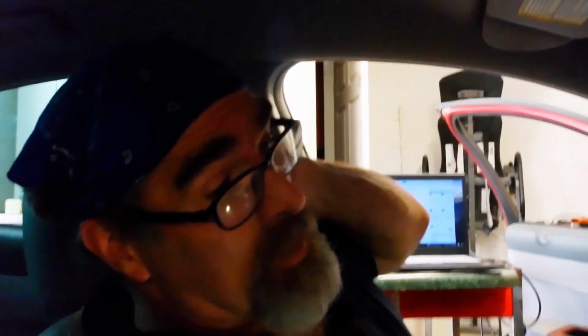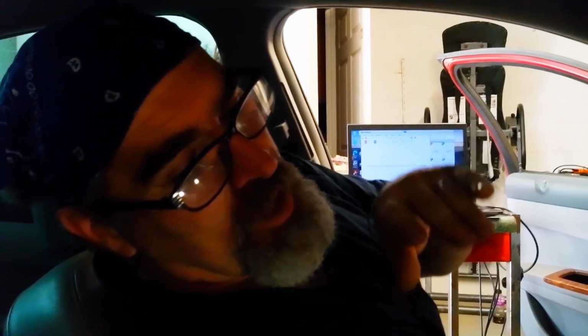So as far as communication on this, if we continue to set communication codes, we have to be losing either a power or ground to this module, or there's an internal problem with the module, or one of the outputs is pulled down. Now, I got in there and issued a two-way command through the scanner to this module to actuate the blower motor, and it's not functioning. So right now I'm suspecting outputs, but we have verified good communication wiring between the module and the splice pack. So I'm going to check these outputs.